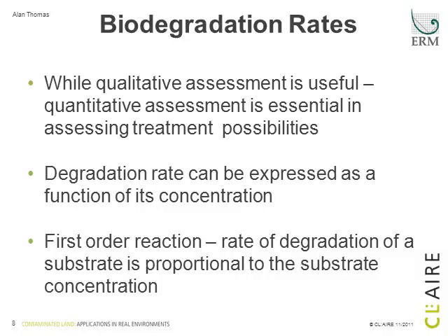to try to optimize the design of the process such that it is maximizing biodegradation rates. Very often biological processes follow first order reaction kinetics, where the rate of degradation of a substrate is proportional to the substrate concentration.